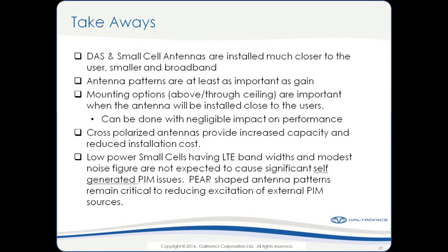And then the final conclusion from today's seminar that I'd like you to think about is the lower power for small cells that are deployed with, well, I should say LTE small cells, not 3G small cells, but the LTE broadband signals, small cells have a modest noise figure, so we don't expect those to be significant self-generators of PIM.